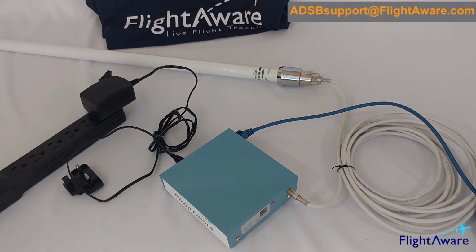Wait approximately 5 minutes and check your ADS-B stats page, which will be a link at the top of the FlightAware webpage when you are logged in called My ADS-B. The stats page won't be available until your site has received a signal and sent the data to FlightAware, which could take a few minutes or longer depending on your location.